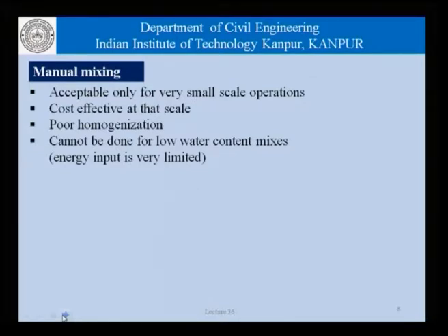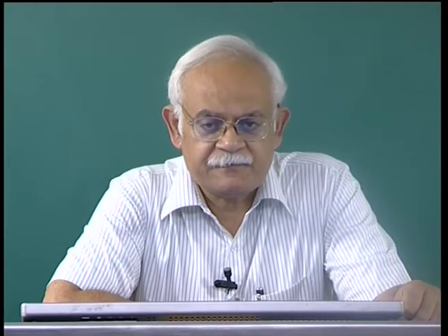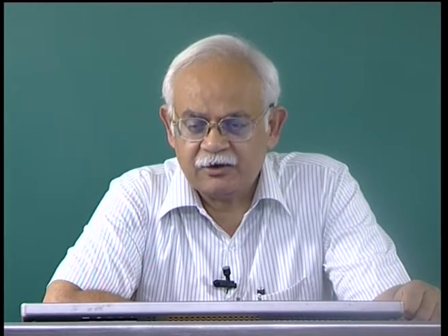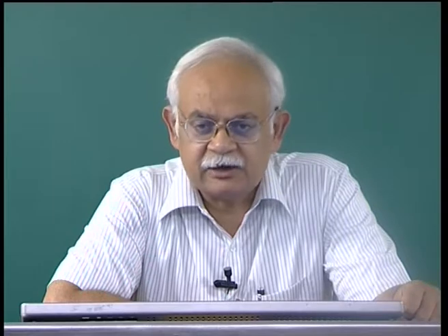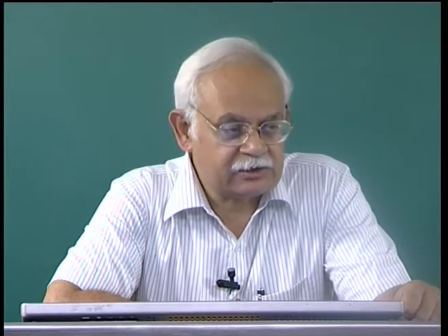It is cost effective at that scale, because if we insist that for those kind of operations involving say 10 liters or 15 liters of concrete, we need to have a mixer there, it might become very expensive. But that is something which the engineer has to decide, because there is a compromise involved as far as the quality is concerned. So, if the decision is made that quality must be maintained at all costs, then regardless of the cost, hand mixing may not be allowed.